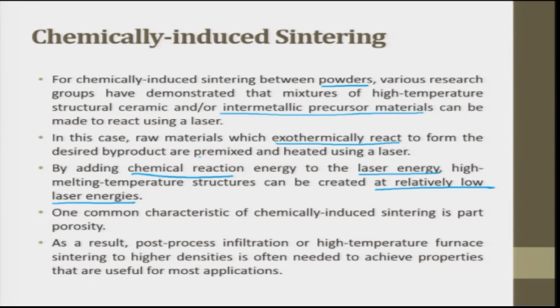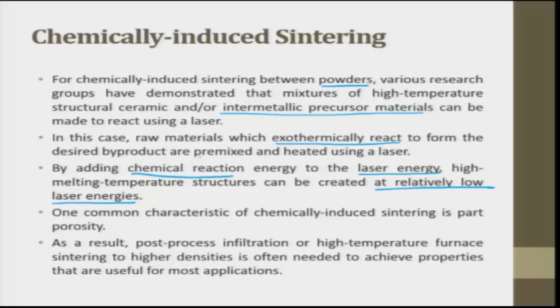Why is this an important factor? Because the more energy you need for the sintering process, the cost of the machine goes very high. Sometimes it also demands subsystems. When the power is enormously high, it needs subsystems for cooling the laser system. So if I can reduce the power of the laser, the subsystem requirement goes down, so the machine price will also go down. By adding chemical reaction energy to the laser energy, we have reduced the laser energy requirement.